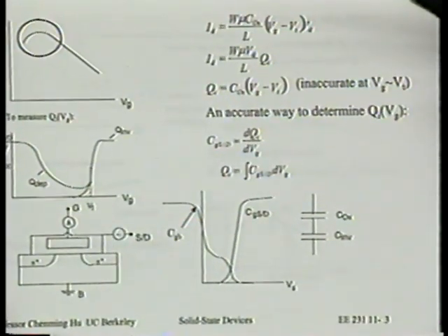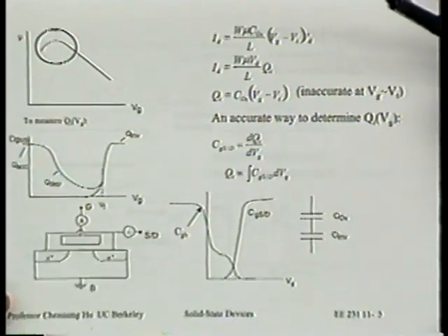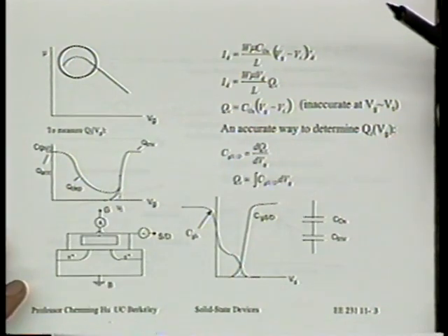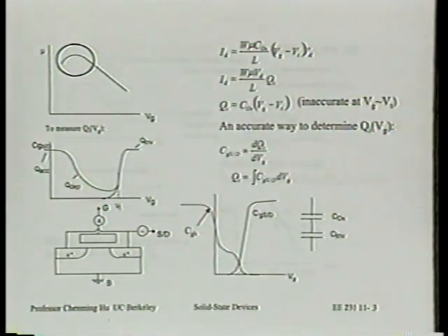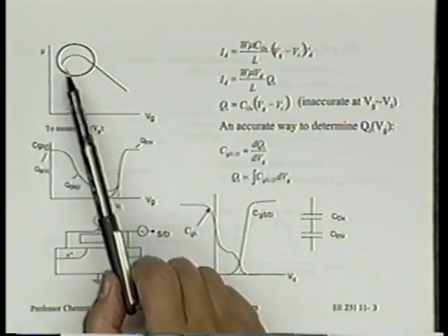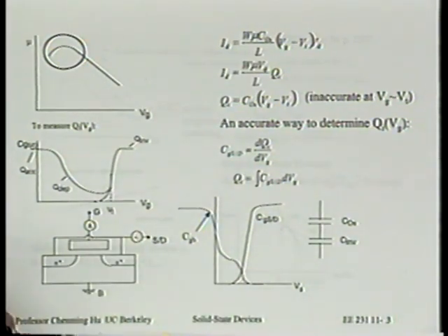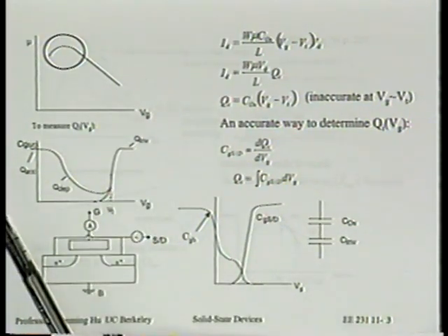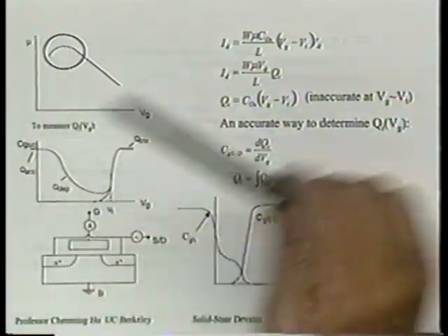Before we explain how to understand and simplify this complex situation, let me say a few words, a bit more, about the measurement. When you make the measurement, you will find mobility does decrease with increasing VG. I already mentioned that. As VG increases, mobility decreases. But you also will see when VG is low, mobility also decreases.